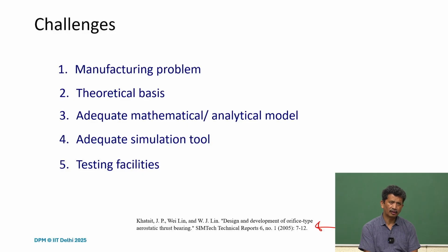The other thing we also understand is that the manufacturing part is not an easy task, and there are limitations. Getting a flatter surface may not be easy. Even the bearing pads have to be diamond turned. So we have to really get a clean and flat surface. Sometimes it's aluminum, and it can be a mirror finish. Those things we have to be aware of.